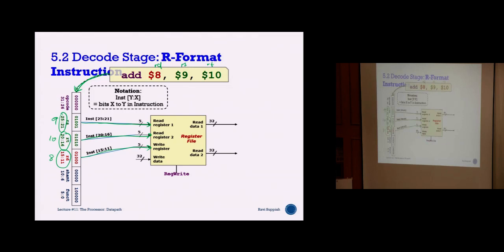So effectively, you can see that I have 5 bits here. Why 5 bits? Because your register file has a total of how many? Total is 32, correct? That means if I want to select any of the 32, I need to specify 5 bits. If what goes in is 0, 0, 0, 0, 1, that means I'm talking about register 1, and I'm supposed to go inside here, take the data in register 1 and bring it out.